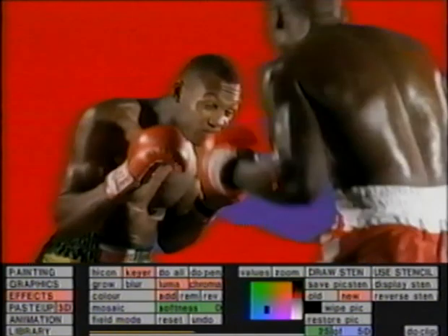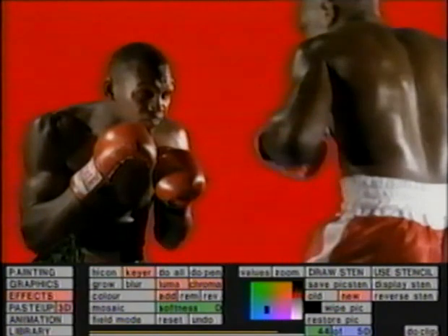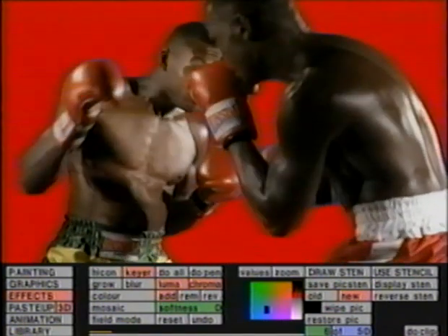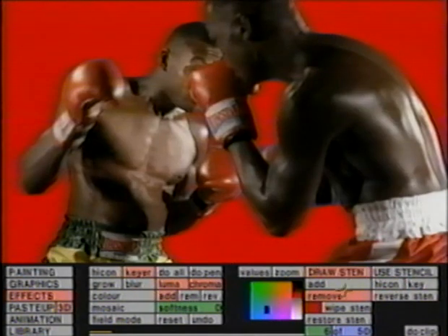Moving through the clip, we can check the key signal is holding for the whole clip. The lighting may change during the shot, for example. Having set a basic key, we can examine it in high contrast and see its effect over a background by selecting Draw Stencil.